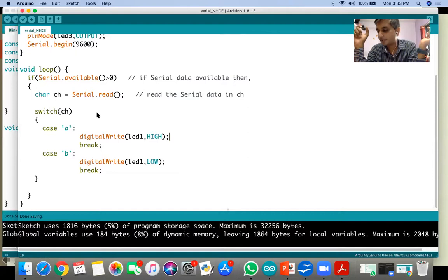It requires the interface because Arduino cannot understand that. Yeah, digital. If it is digital, then how many bits is that microchip antenna giving data? 10-bit data, 16-bit data, or how much data? If it is 8-bit data, then it is okay, because your Arduino serial port is supporting the 8-bit. Yeah, 8-bit. Then definitely you just need to convert that.